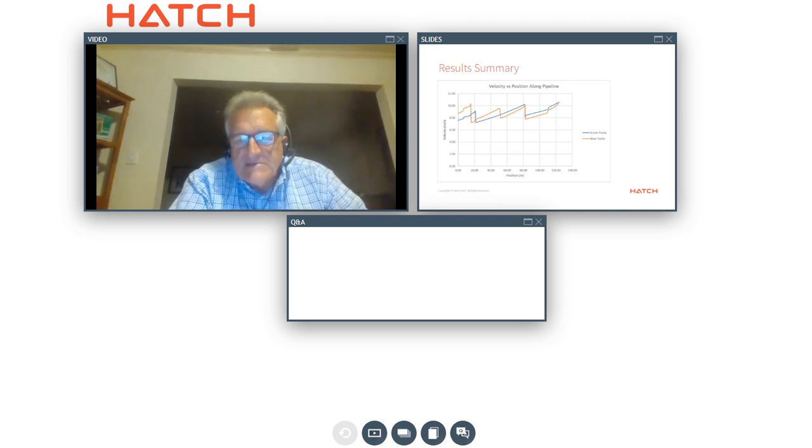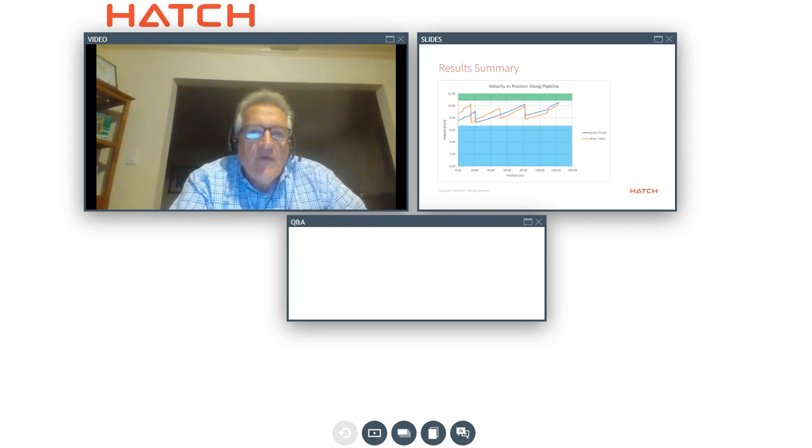Now the next slide takes this same chart, but it adds a little bit more information. It actually shows you where the dense phase portion of the analysis would have taken us with that large blue section, and where the dilute phase, or the green portion of the calculations, would have taken us had he used lower velocities, lower air volumes, or higher air volumes respectively. So basically that zone in between the green and the blue is the yellow zone, or the 2-phase regime that we wanted to stay in.